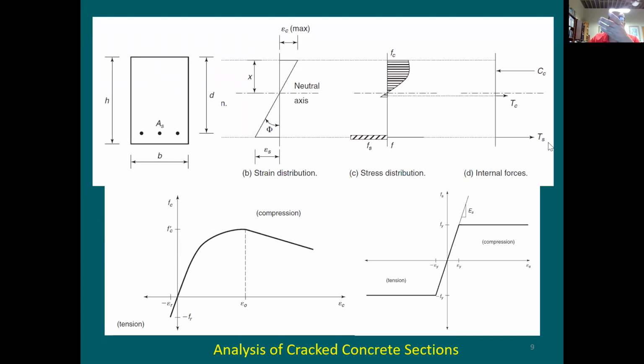How about the forces? Now I need to determine the internal forces. These are not external forces. External forces means like dead load, live load, some loads that you put on top of the beam. This is now going to be internal forces. So, okay. How much is the tension in the steel? When you have any steel, you have a uniform stress of Fs, and you have As. Tension force equals what? As times Fs. Because what does stress mean? The stress is equal to a force divided by a cross-section area, like normal stress, uniaxial stress. So the tension force equals As times Fs. And with that, I have the tension force.